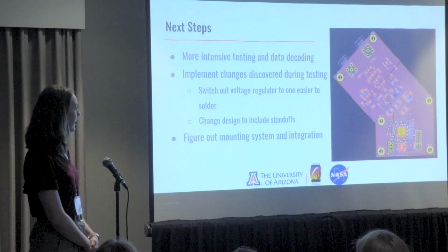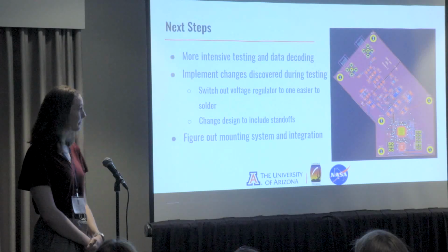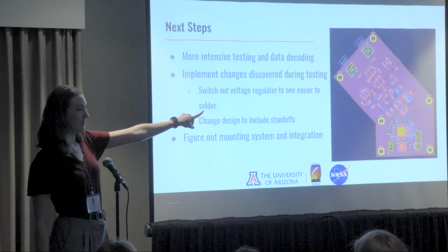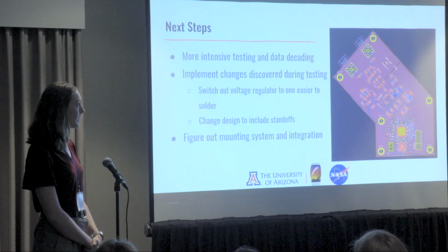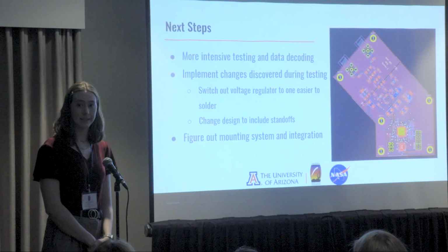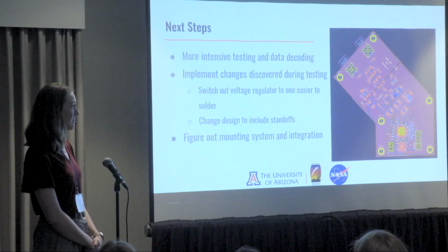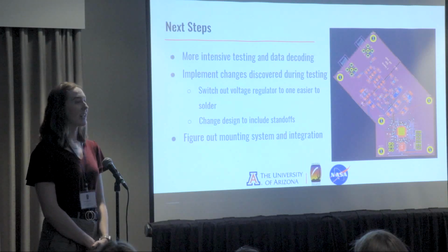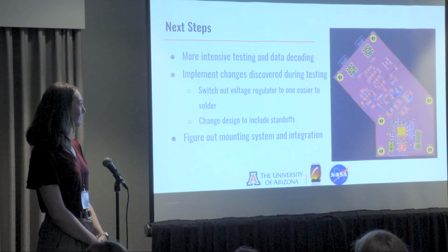Before we started testing, we already knew we needed to switch out our voltage regulator to one that's easier to solder. We also changed the design to include standoffs, which is shown over here, which will just make it easier to handle. I've also been working on another version of this PCB that has a different model of ADC in it. During our initial testing, we discovered that our PCB draws a lot more power than we anticipated and can realistically supply.